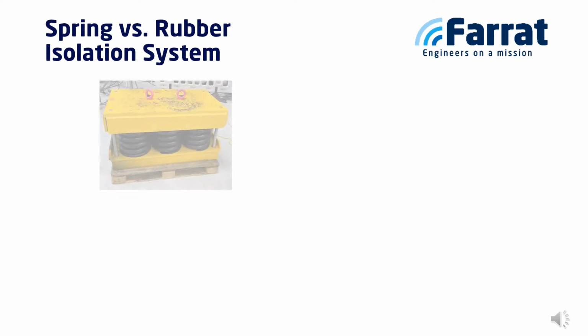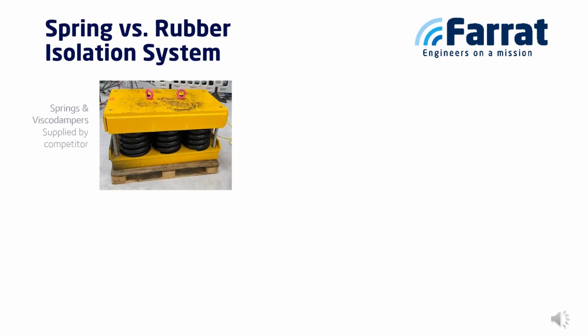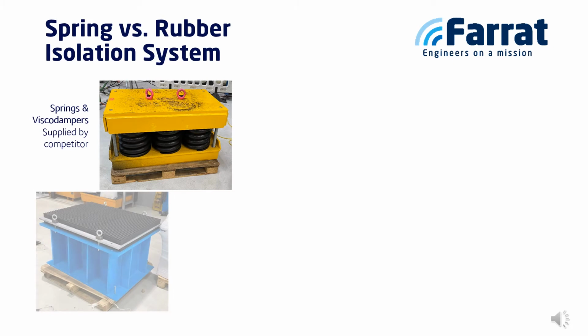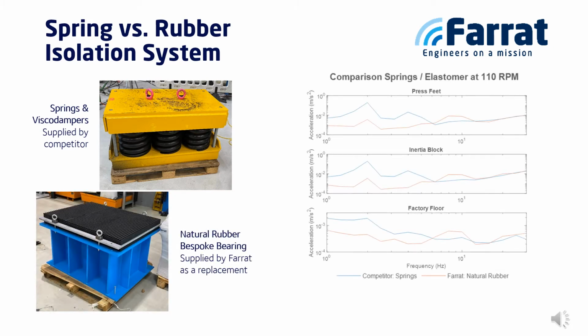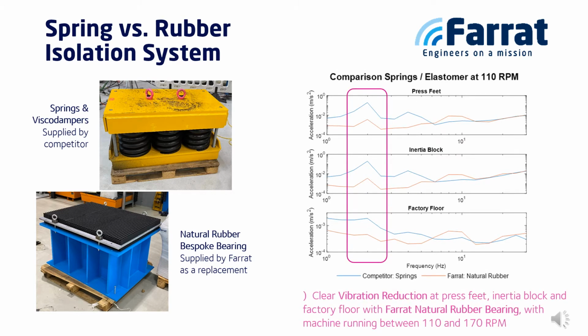Another real-world case study can also be presented to highlight the performance of Farrat isolated foundation designs. In this instance, a can factory was having issues with a copper press, generating excessive vibrations that could be perceived by neighbouring buildings that were placed at a distance of 70 metres from the machine. A study performed by a consultancy specialising in vibrations and structural dynamics concluded that in order for this press to be properly isolated, a natural frequency of 1.25 Hz should be achieved by the isolation system.